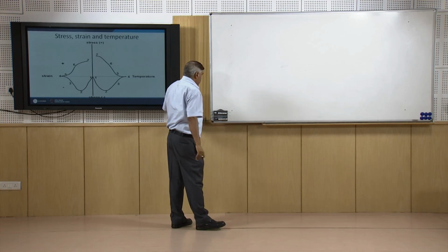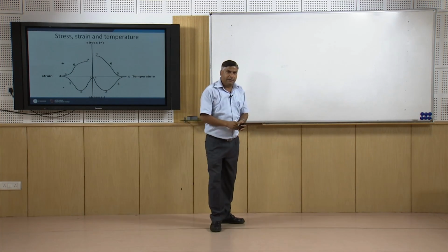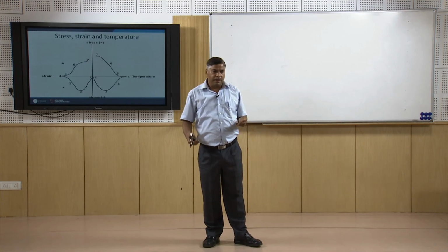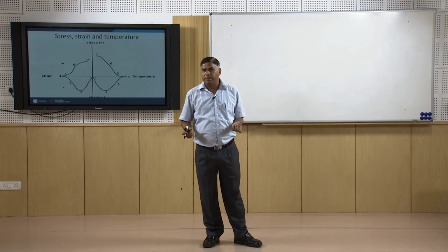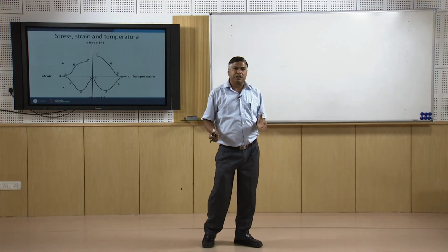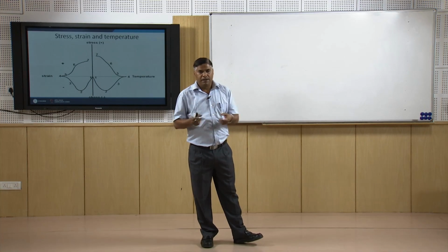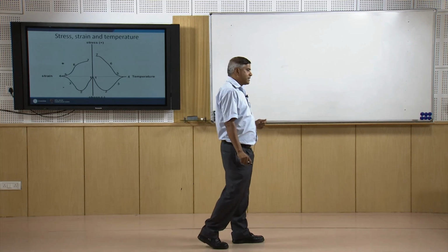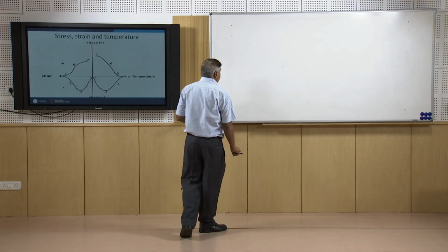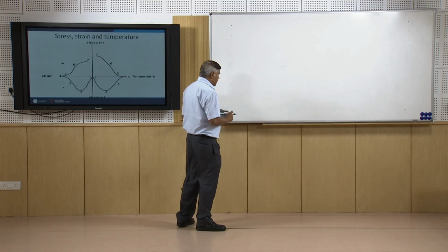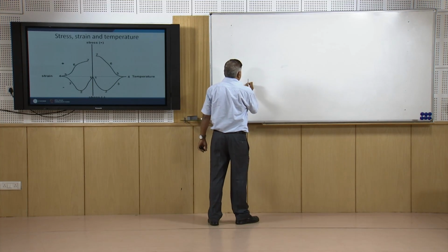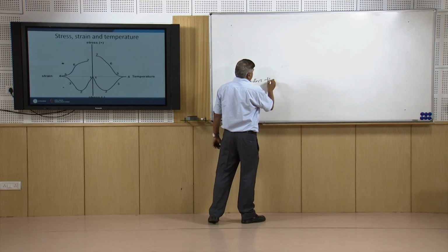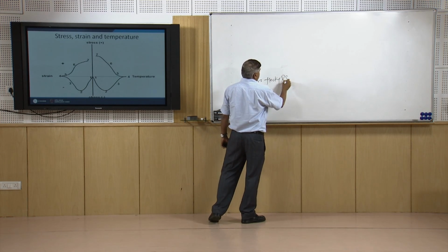So, what we have seen is that the tensile residual stresses basically develop along the weld center line, and when transverse shrinkage takes place due to the shrinkage of the weld metal, if the plates are kept under very restrained conditions, that also develops tensile residual stresses in the weld. So, now we will see how these factors affect the residual stresses.